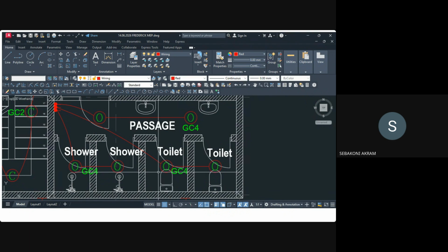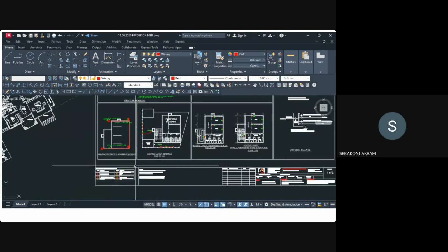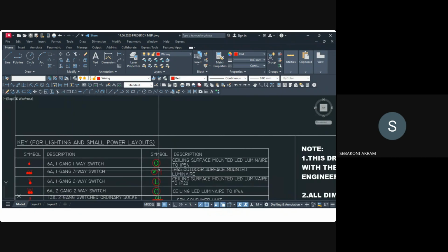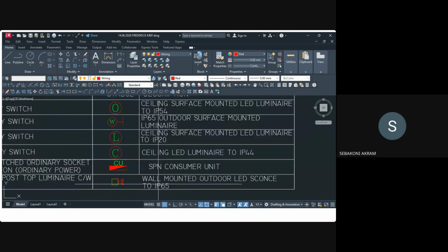Also for water resistance, there is IP65, which is for the outdoor, but for the bathroom, since it is just enclosed, you expect water to just splash onto the bulb. So the IP is different from when we have outdoor lighting. You're getting me, like now this one of IP65.